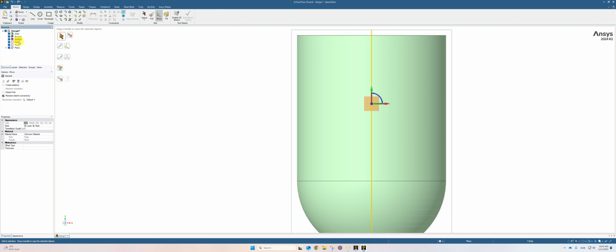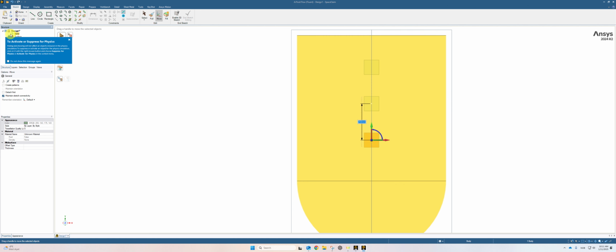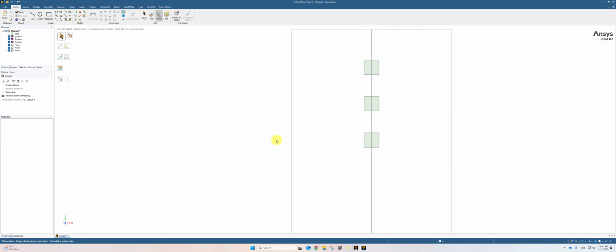So if I repeat this process, Control C, Control V, and then click on the third surface and then move it for another 250. All right. Now you have three surfaces that I'm going to pull on both sides. These are going to be my inlets, okay? So let's unclick the solid and then you have three surfaces, right? Which I'm going to pull.